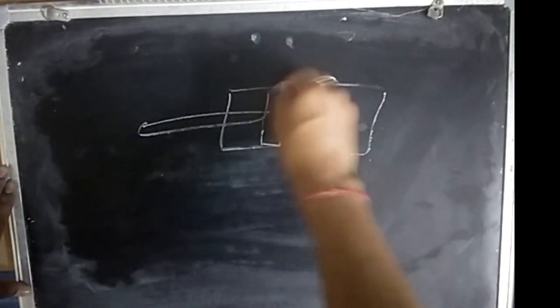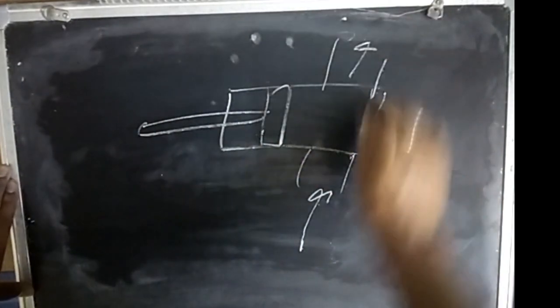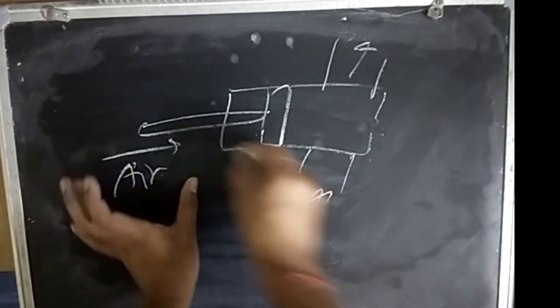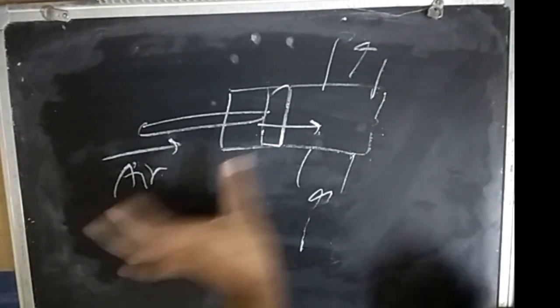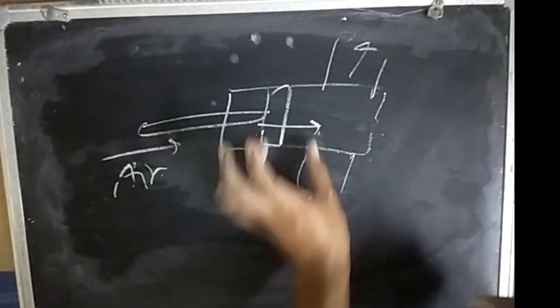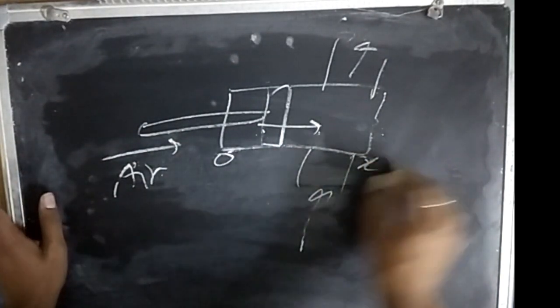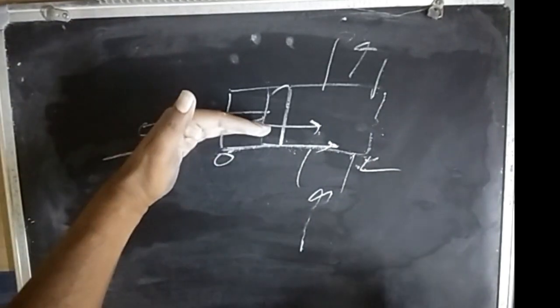Okay, next thing is valve, air pressure, air to open. If this is my valve, fluid is coming, air is going up. So if my air pressure increases, air to close valve means I'm putting air and this is closing. So this is direct acting. Why? Because I'm putting more air, and this stem moves from 0 to L distance, moving this way. So as air increases, the position also increases.